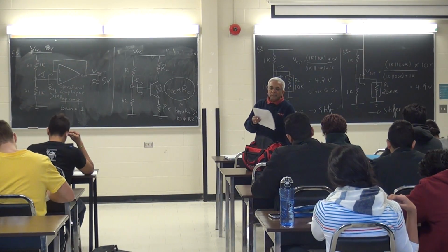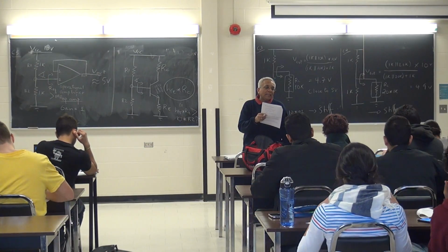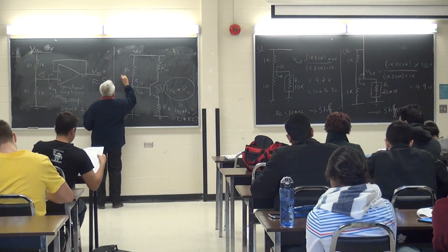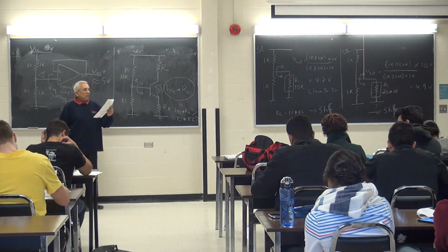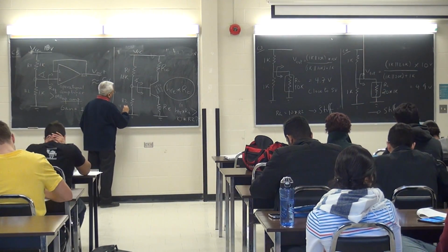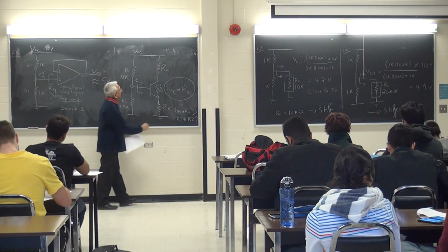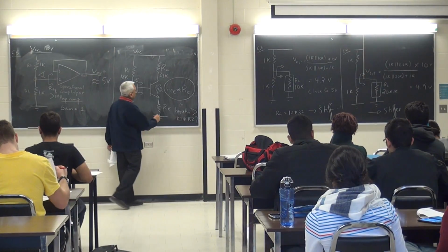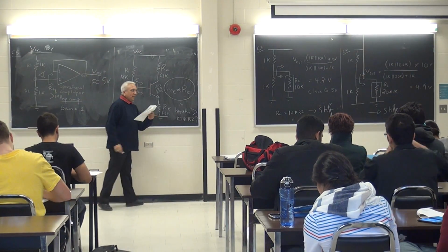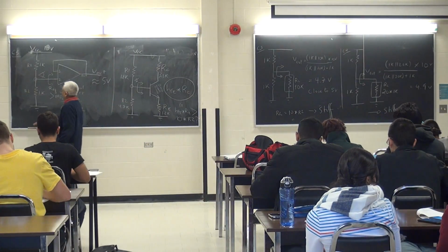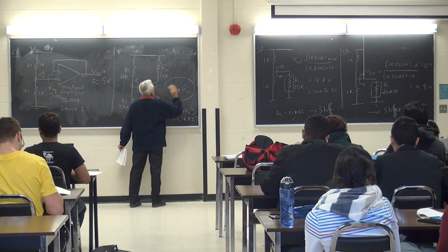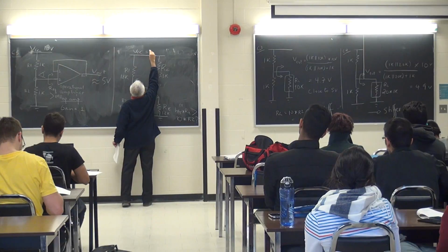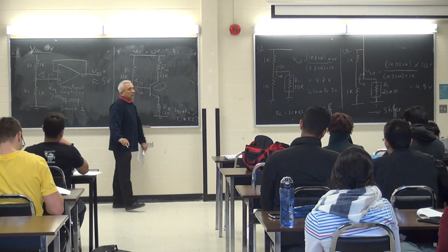I'm going to put some numbers to this circuit and see if it is stiff or not. I'm on page 3, everyone. R1 is 18K, R2 is 4.7K, RC is 3.3K, RE is 1.2K, HFE is 150, and VCC is 10 volts. Okay, so there's my circuit.